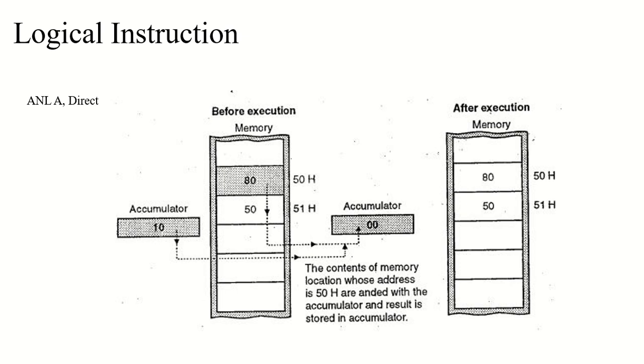This instruction consists of 2 bytes and 1 clock cycle. We are using direct addressing mode, as you can see, and as simple as that, because we are performing a simple AND operation, there is no flag which is getting affected. And I have mentioned an example here. Let's take ANL A comma 50h.